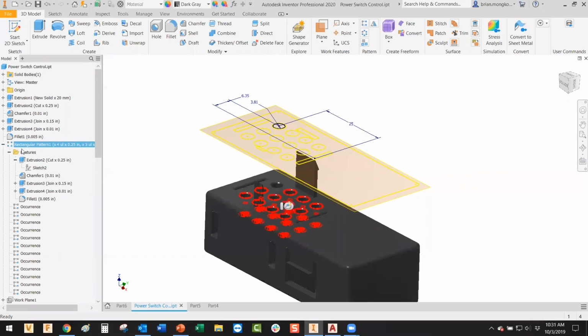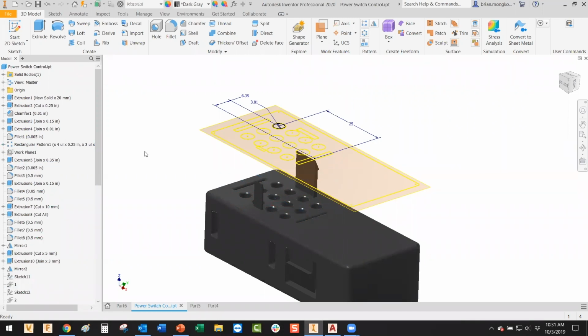And then if you want to edit just one of these hole cuts, like you want to change the size of the hole, the diameter, you can do that at this level. If you want to change the depth of cut, for example, you could do it there. So you have different layers in which you can do it, but it's a lot easier to understand something like this rather than having all of them jumbled into this sketch here. So just best practices to abide by.